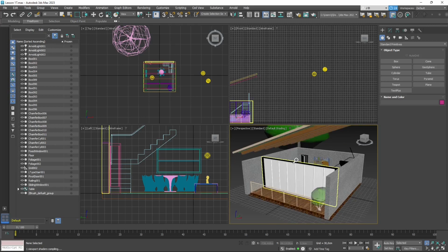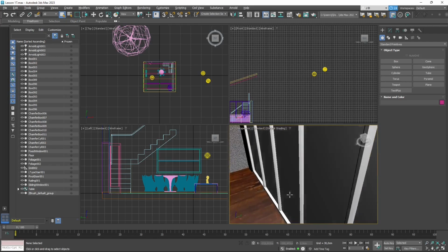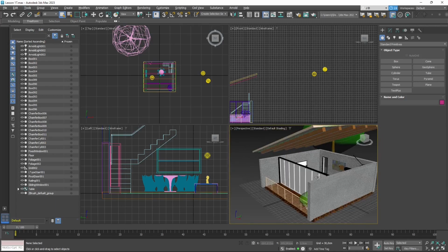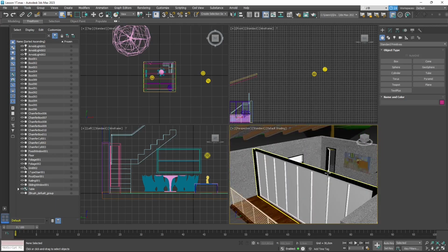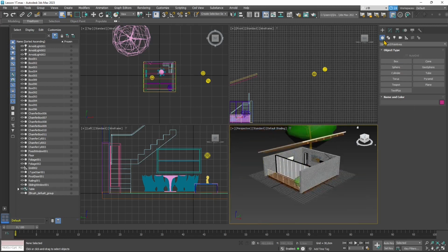So in the previous videos, we saw how we can create standard materials, basic materials, using the PBR basic parameters and channels, like the diffuse and the roughness. We applied also textures using these same channels: the roughness textures, the diffuse texture, and also the bump and the normal texture to create some fake 3D effect on the walls here, for example.